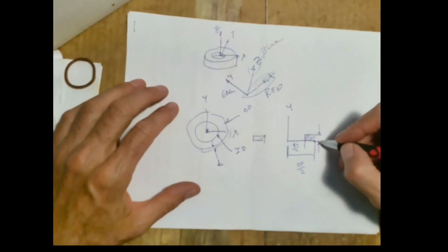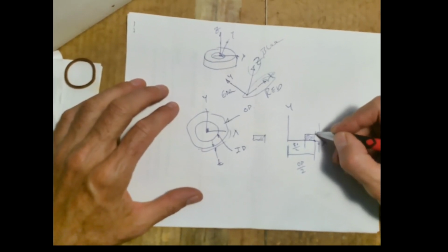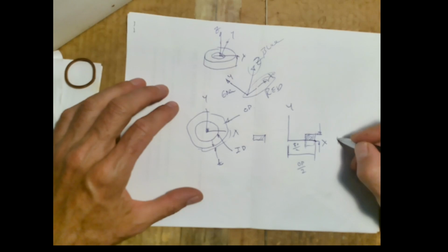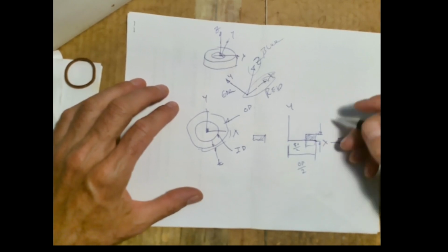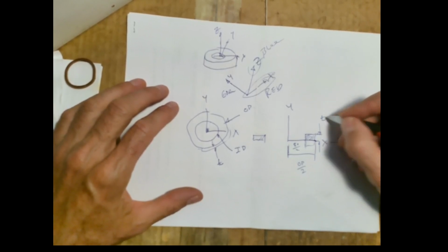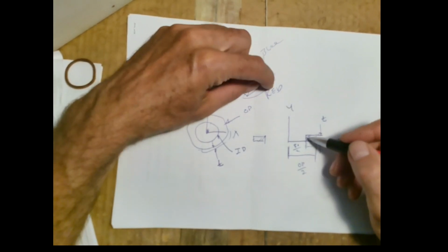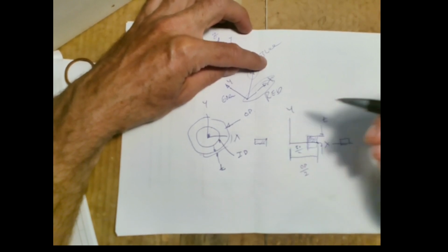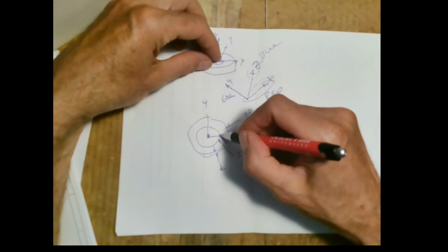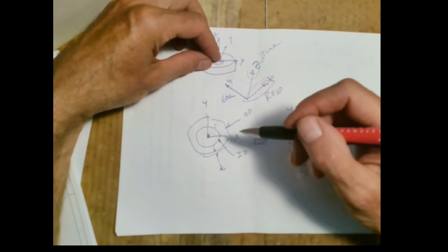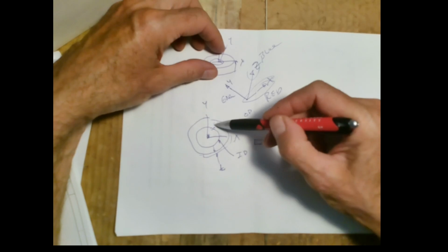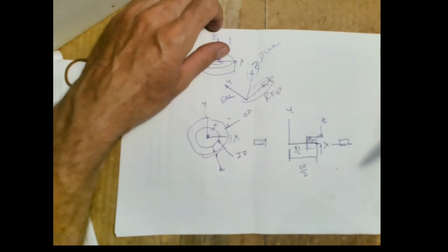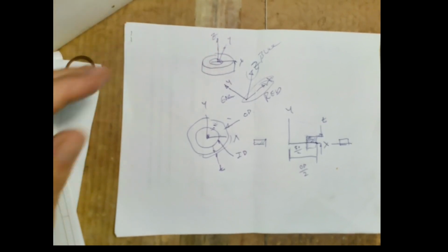There's three choices, right? You could have it above the x-axis, you could have it below the x-axis, or you could have it on the midplane of the x-axis, depending on what you're going to do. But anyways, that would be the thickness. And then this cross-section would be revolved. Whereas over here, we'd be extruding, or padding, what we call a pad, the annular circle to make the washer. All right, so that's kind of like the theory.